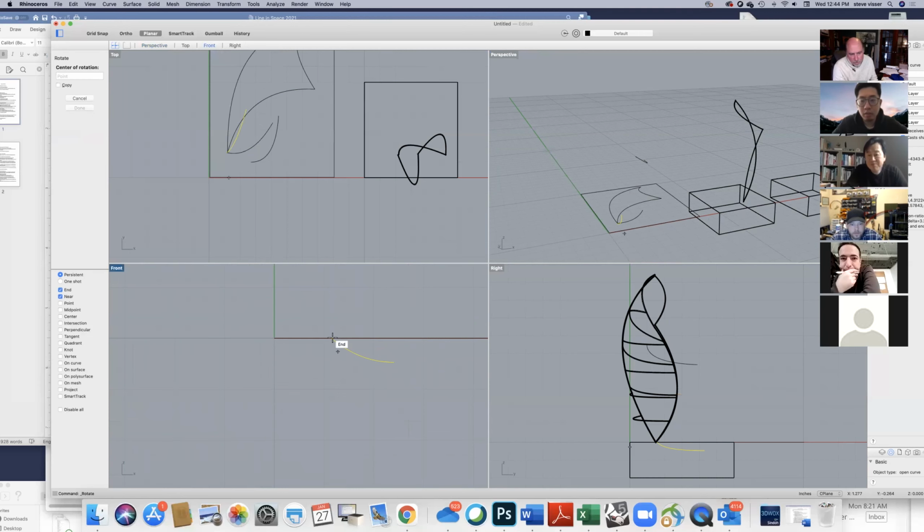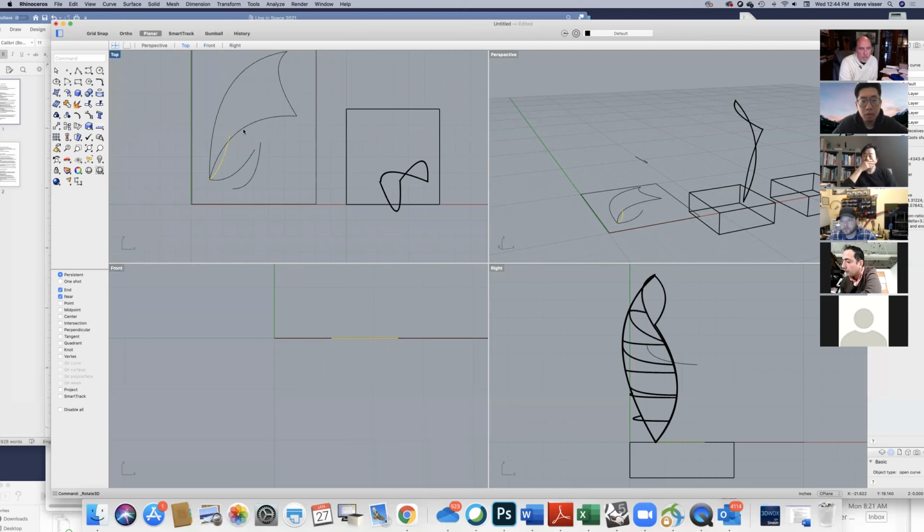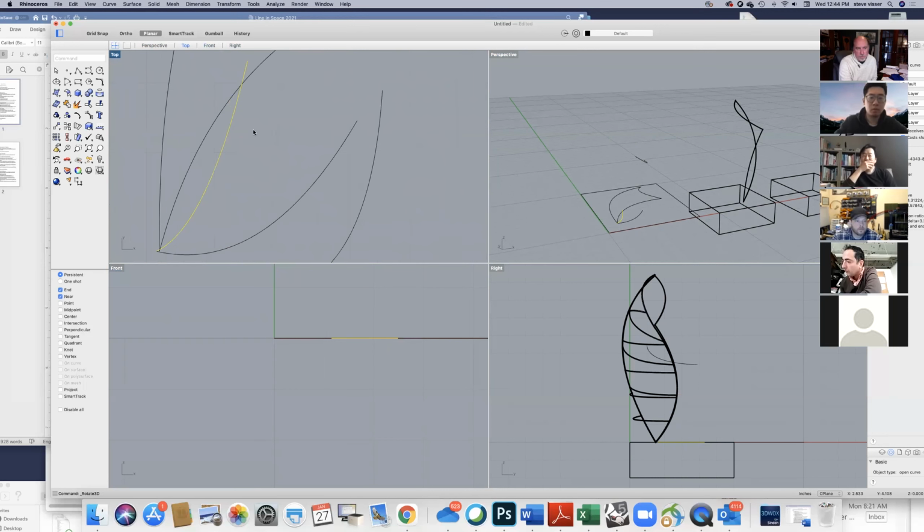2D rotate, endpoint, endpoint, and endpoint. Now I'm going to do 3D rotate, endpoint, endpoint, a point nearest, and then hold Shift to make it horizontal. Okay. Now, right now that arc is sort of crossing there. I can rotate it again so that I don't get confusion there.